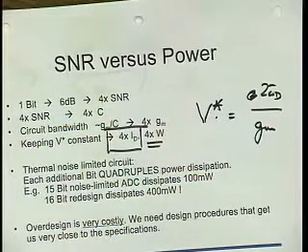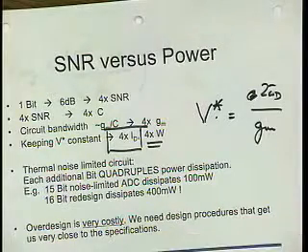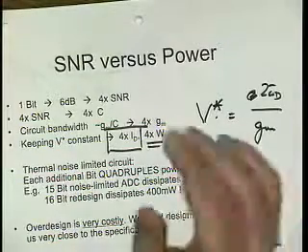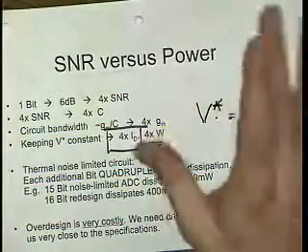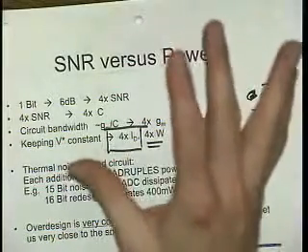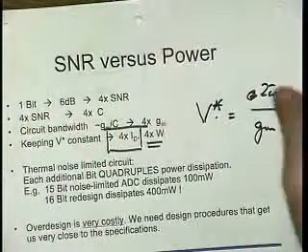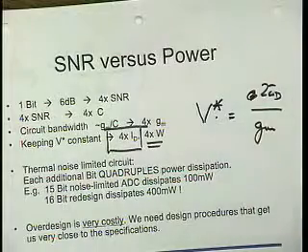If you need to build an A to D converter or a circuit, a function, that needs a signal-to-noise ratio that corresponds to 12.5 bits, it's just 12.5 times 6 dB plus 1.7. Then you're going to build a circuit that has that 12.5 bit equivalent resolution, not 13 bits or 14 bits or so, and certainly not 16 bits.